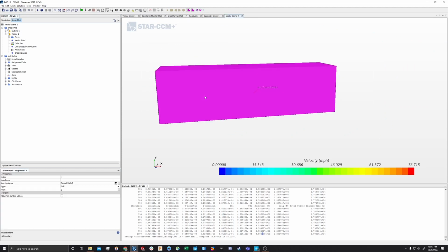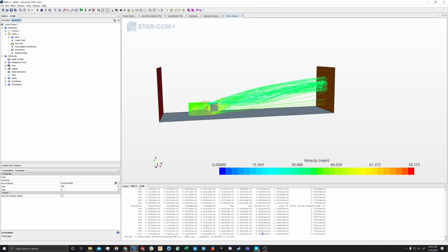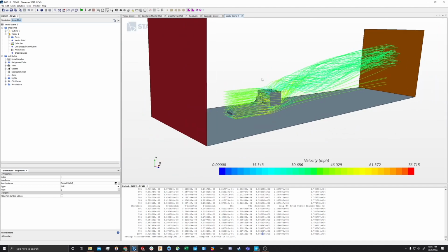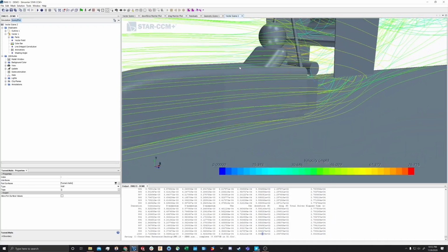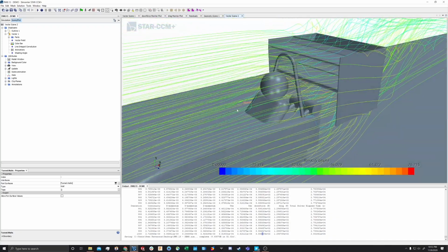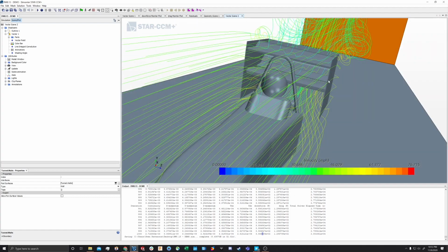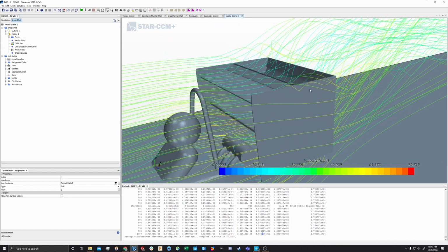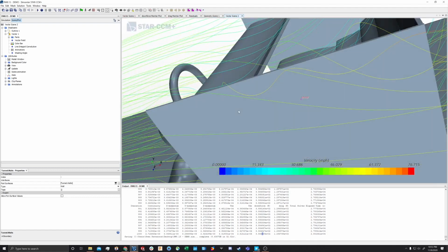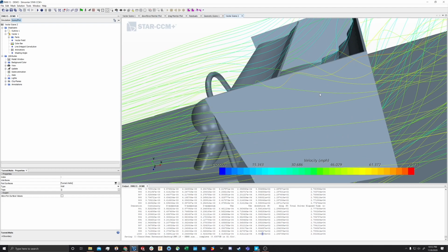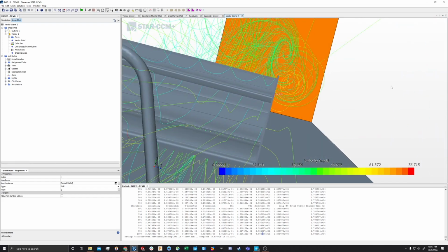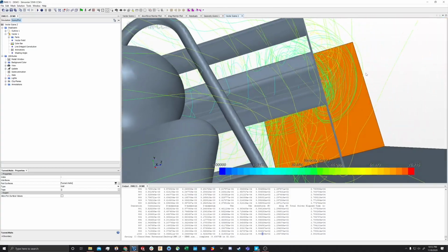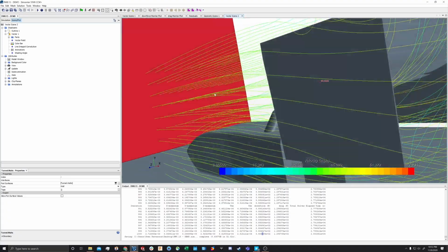We've got all our surfaces in there. We can go ahead and hide this outer surface. You can hide other surfaces that you may not necessarily care about right now. And now we can see these streamlines going around our body, with nice velocity indicators, so we know how fast the air is moving. You can see we've got some really quick moving air on this vortex that we're getting off this top biplane wing. But yeah, this is a great way to go in and analyze little components of your wing and see what's going on there.